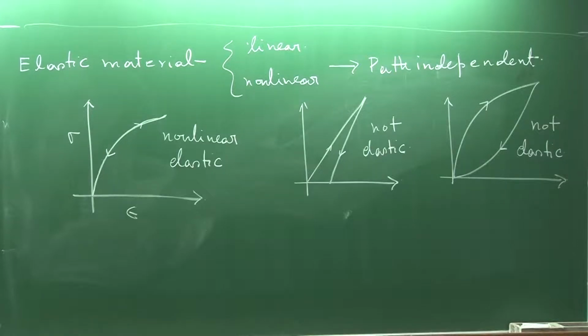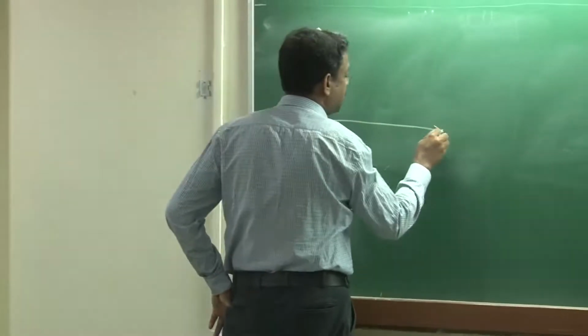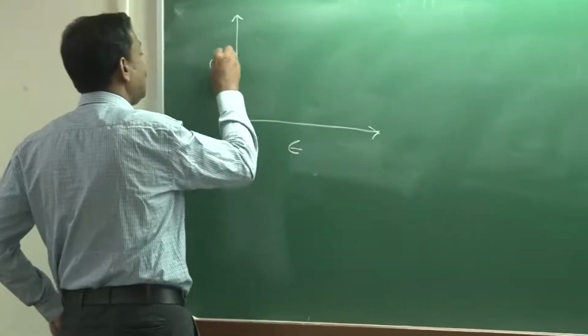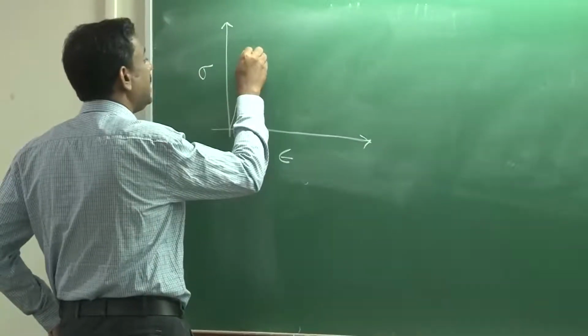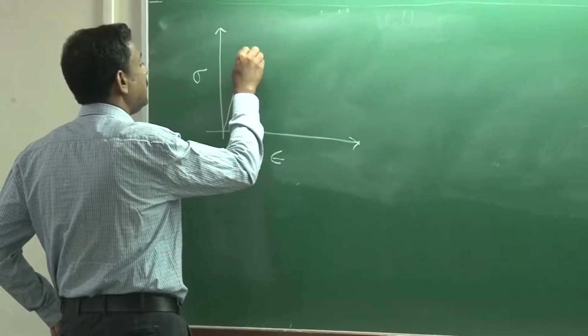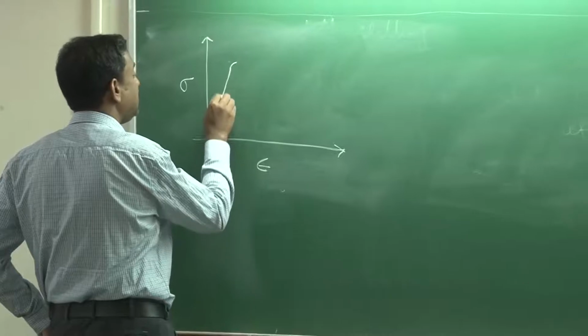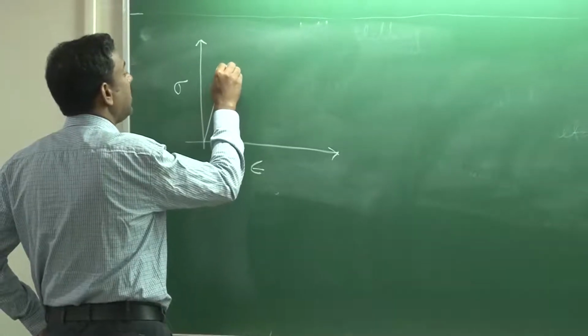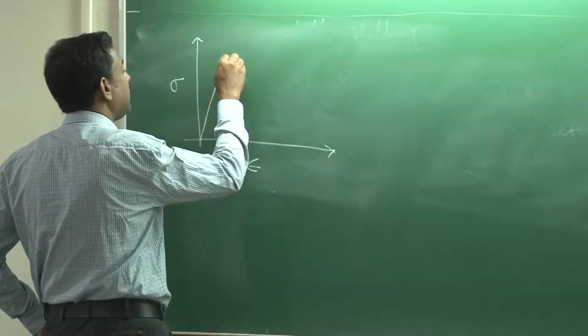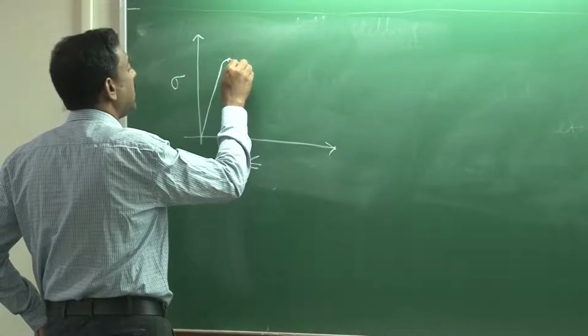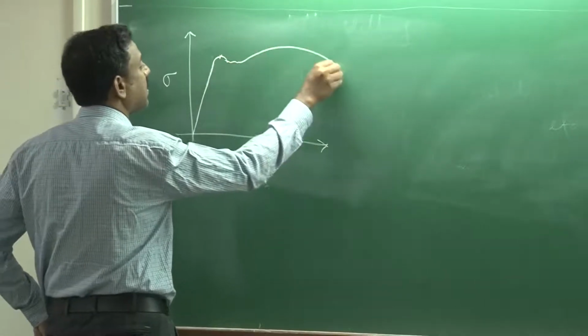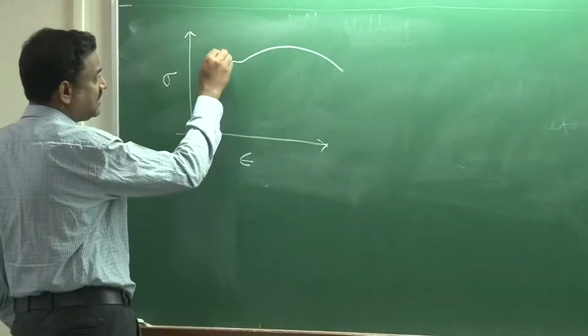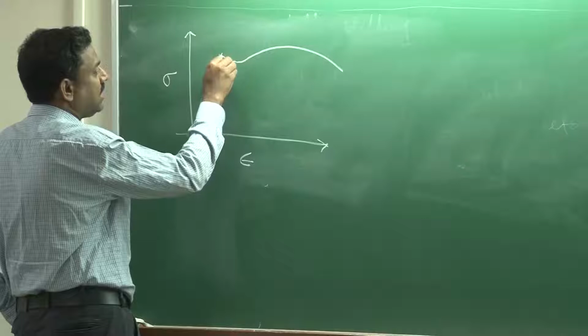when you do the tensile testing on steel, the stress-strain behavior, epsilon and sigma, was linearly elastic, and after that there was this thing. Until this point was the proportional limit, but thereafter there is the first yield point, the upper yield point, and then the second yield point, the lower yield point.